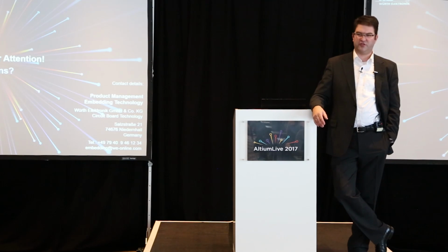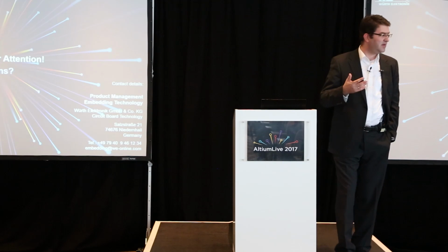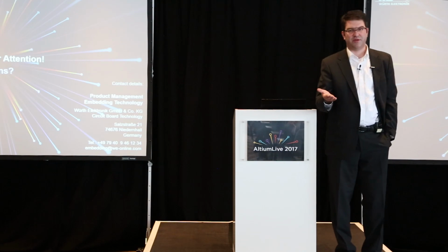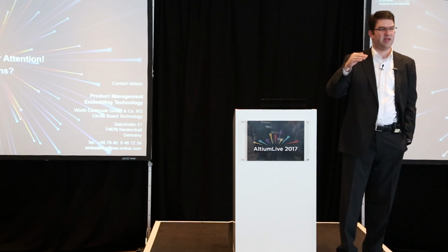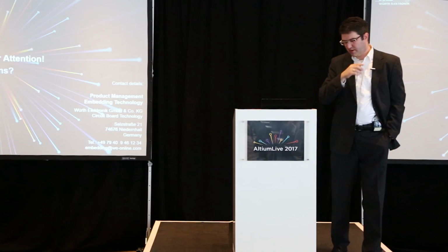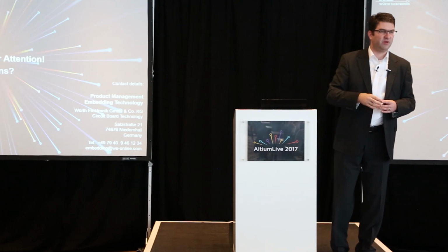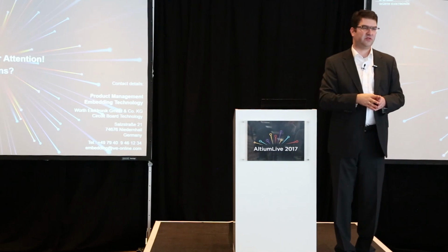Regarding yields, to just give you figures, it depends really on the complexity of the components. If you have a packaging application with one component, we are at yield rates up to 99.5% already. The more complex the board gets, the yield will go down, but still we need to stay in the area of 95 plus.